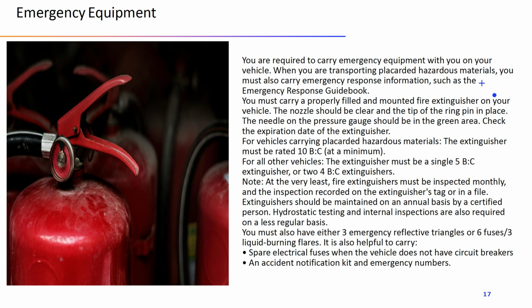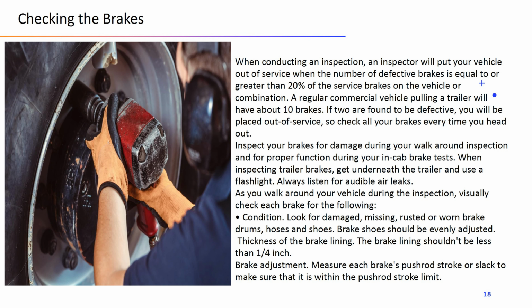Note, at the very least, fire extinguishers must be inspected monthly and the inspection recorded on the extinguisher's tag or in a file. Extinguishers should be maintained on an annual basis by a certified person. Hydrostatic testing and internal inspections are also required on a less regular basis. You must also have either 3 emergency reflective triangles or 6 fuses or 3 liquid burning flares. It is also helpful to carry spare electrical fuses when the vehicle does not have circuit breakers, an accident notification kit, and emergency numbers.